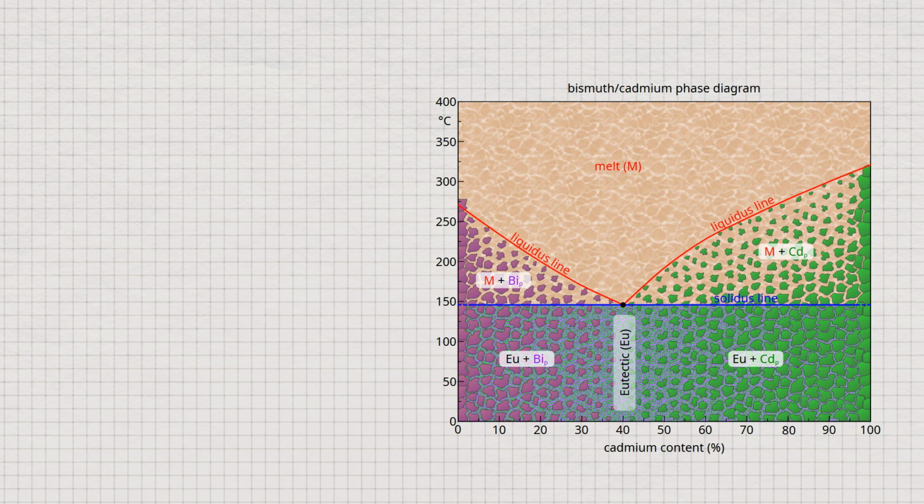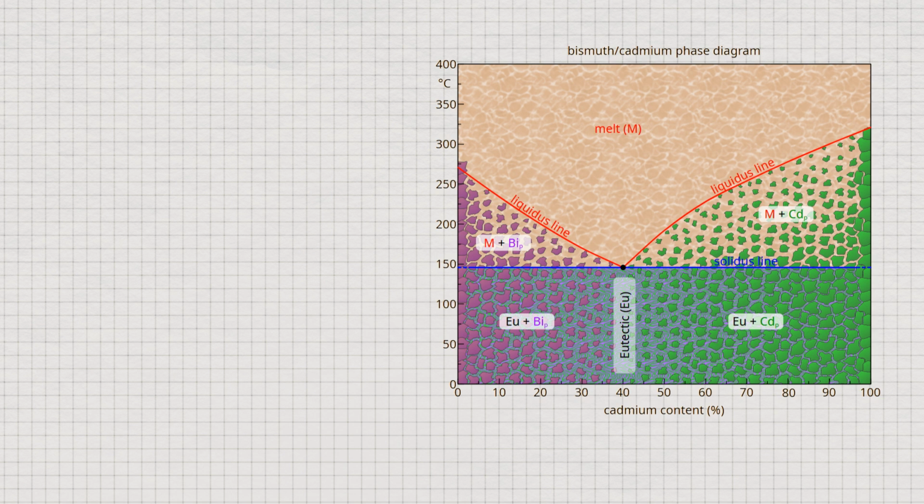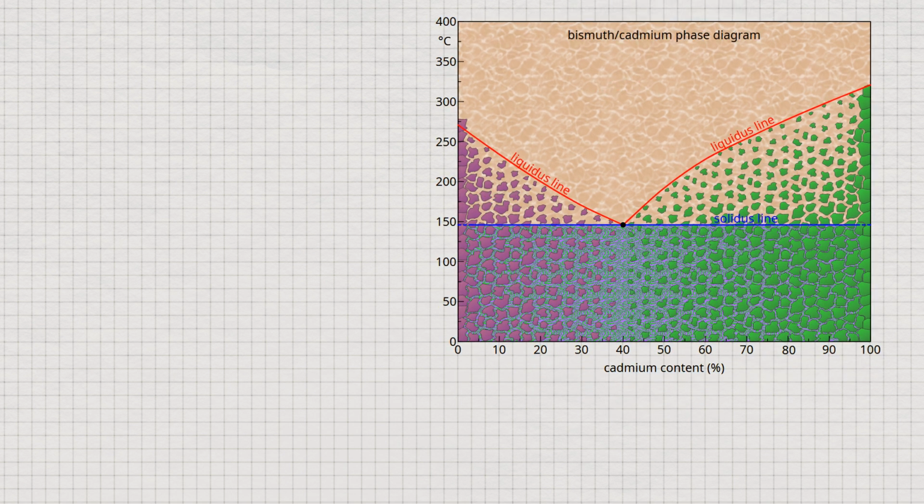It should be noted that as the alloy concentration approaches the eutectic composition, the grain size of the primary crystals decreases. This is because the alloy concentration is already close to the eutectic point. Therefore, only a small amount of primary crystals will precipitate to reach the eutectic composition for complete solidification. The microstructure fractions, that is the proportion of the eutectic or primary crystals, shift linearly with a change in the alloy composition due to the lever rule.